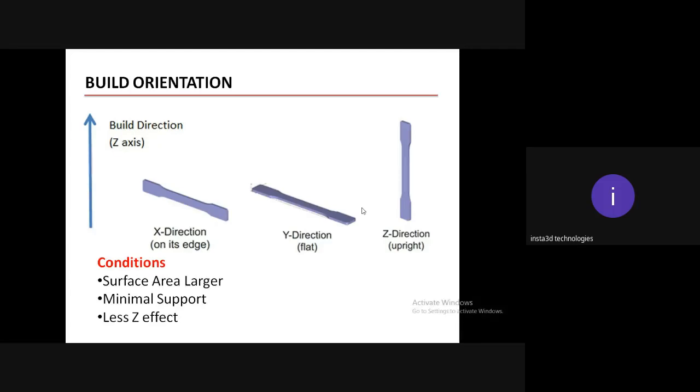Z effect may be less compared to the third one, but even so it is not recommended. The third one has a lower surface area, not recommended. Support, the lower parts, it always has a support, so not recommended. And Z, not recommended. So the third condition is least recommended. The second one is the best recommended orientation.